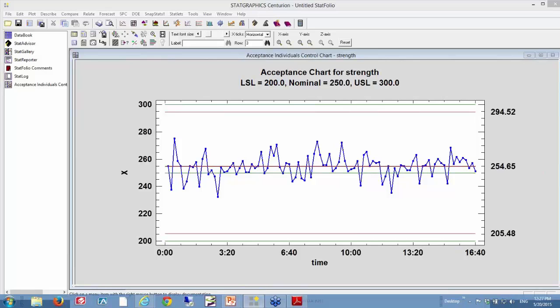All these models assume that there's some random component that's causing the variability that I'm looking at. If the operator is doing it, that's not a random effect, and that's definitely going to violate the assumptions of any one of the models underlying these charts. So I don't think these charts are capable of handling situations where the operator is constantly making adjustments.